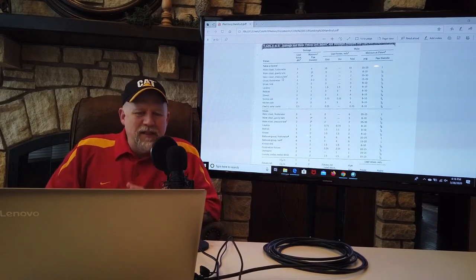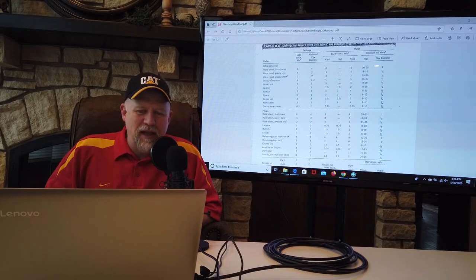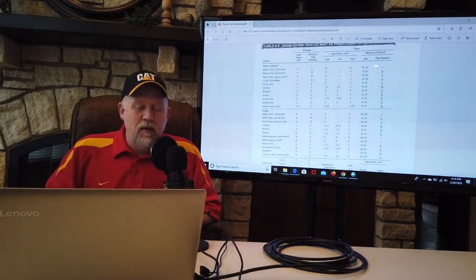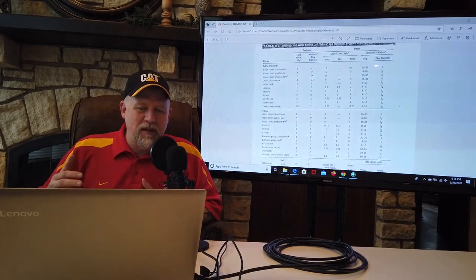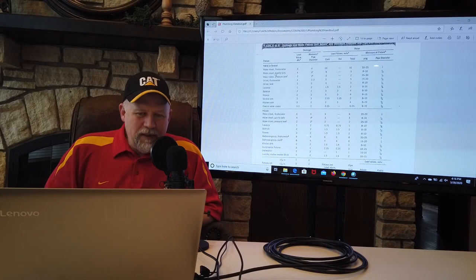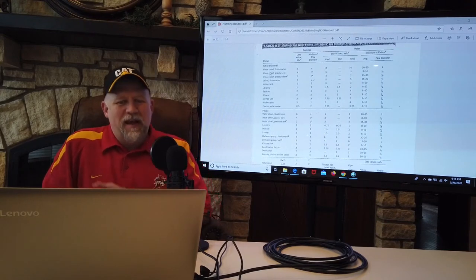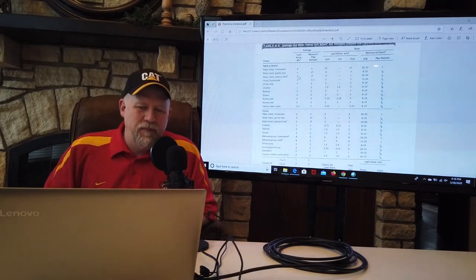Next, there are different types here. There are water closets that are flushometer, which is a flush valve, water closets that are a gravity tank, and water closets that are a pressure tank. The pressure tank is the one that we were looking at, that is the pressure assist. Predominantly, unless it says otherwise, for a commercial building, you're going to be using flush valve water closets. So for this class, that's the only one I want us to look at.